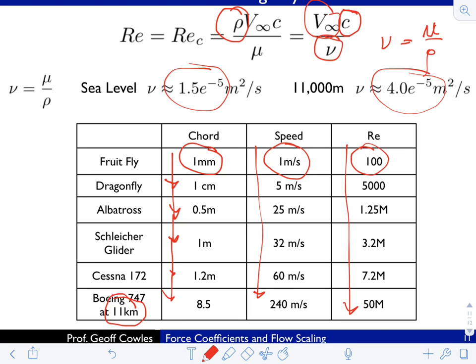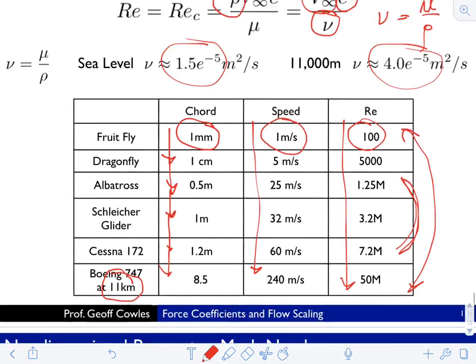So there is a true Reynolds dependency, of course, on the drag, but there will also be one on the lift, as well. When we look at the pressure distributions in a couple of classes, we'll see that in our sort of range, if we're mucking around, say in this range right here, looking at the lift on the wing, there's not that much change to the lift coefficient when you vary the Reynolds number across a range like that. It's a pretty small change, so it's sort of Reynolds insensitive. If you allow yourself to range through this entire range, you will find out that you have Reynolds sensitivity to your drag, of course, as you always do, but also to your lift. We'll look at that more in class.